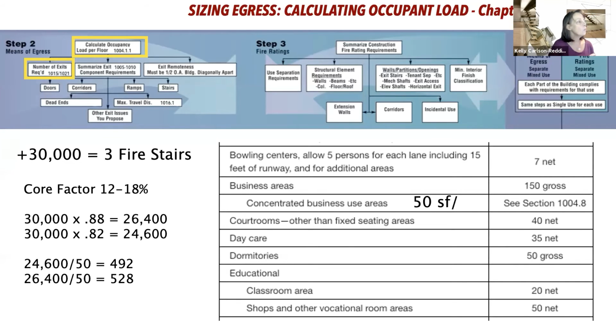When we're trying to calculate the occupancy, when we're trying to meet the intent of the building code, we are thinking about how many people theoretically could be in the building. And that theoretical number is how we determine the sizes of the different systems, as well as the numbers of things like fire stairs, doors, etc. With a high rise, say we've got 20 floors, and this is where that 30,000 square feet starts to be problematic.